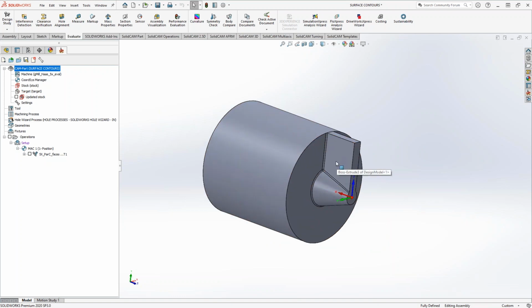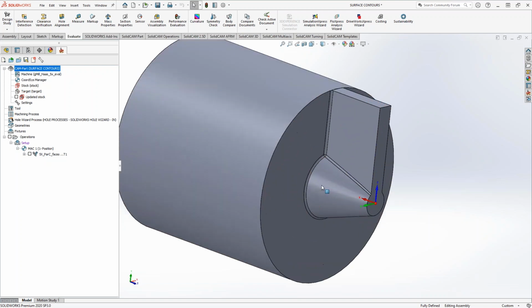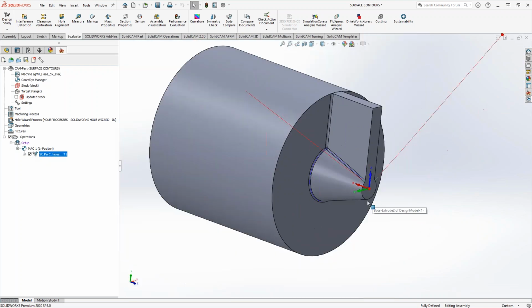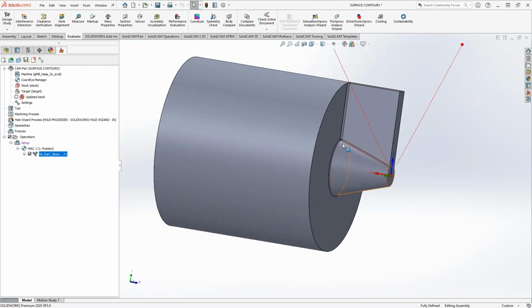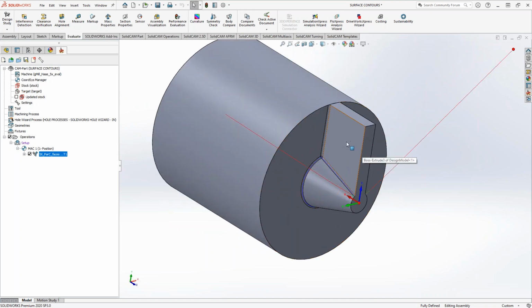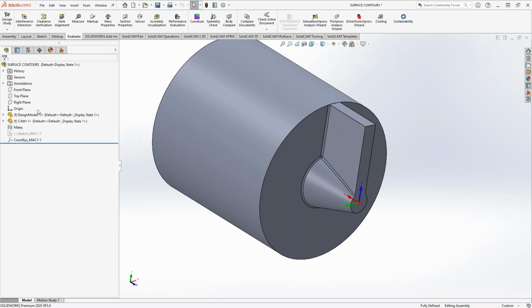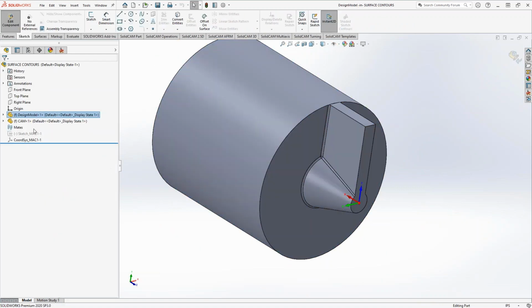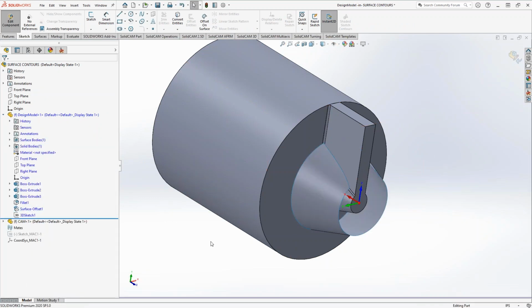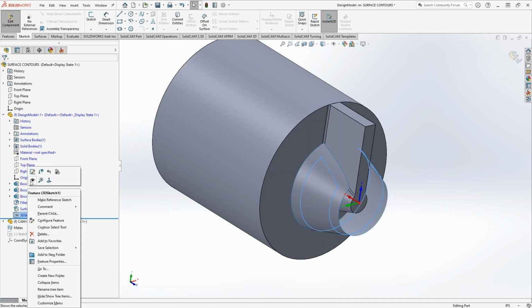But I'm using it here in 5-axis because of what I specifically used this for on a customer part very recently. Let's say I want to do these fillets, and I just want a tool path that kind of looks like this. I just want the tool to come in, go around, do that fillet, and exit without the holder touching these walls, without the tool touching these walls. And the way I did that was I created a surface, and then I offset edges from that surface.